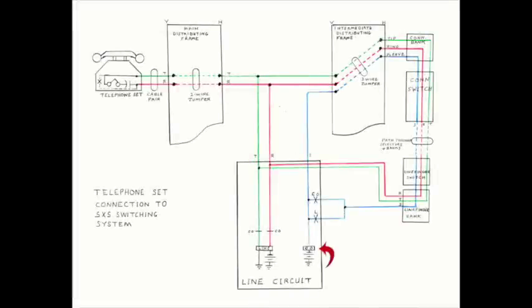It is important that the line circuit cutoff relay operates before the K relay fully operates. This is necessary to cut off the line relay from the tip and ring leads. As soon as the K relay fully operates, ringing current is sent over the tip and ring leads to the called station. It would also be sent to the line circuit if the cutoff relay wasn't operated, causing the line relay to chatter and initiate false dial tone requests.